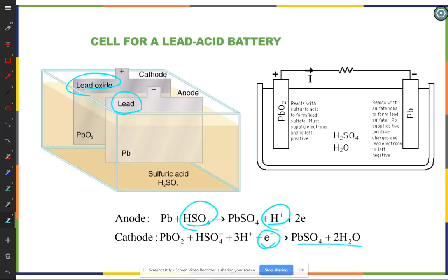So when you test a battery, one of the things that a naive person does is just takes their multimeter and checks to see what the voltage across the terminals is. Well, the terminal voltage should be the full voltage unless your battery is completely shot. But if you're using the battery, if the battery is in good shape, the voltage won't drop very much when you test it in use. If it's in bad shape, the chemical reaction can't work quickly, right? With this battery, if both those plates are now a high amount of lead sulfate, your chemical reaction is not going to work very effectively anymore.